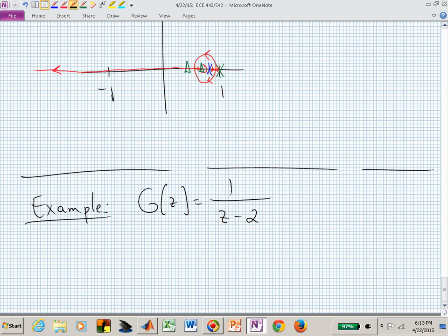But there will be a range of values of gain K that will allow the closed loop pole to be inside the unit circle. You can find the minimum value of K and the maximum value of K for stability, for a gain. But again, the steady state accuracy may be unacceptable. So somebody says, let's design a PI controller for this. And what's the structure for a PI controller?